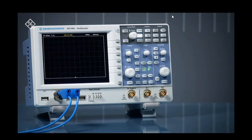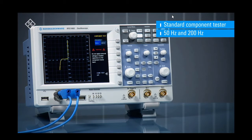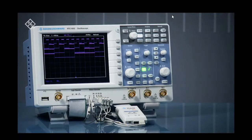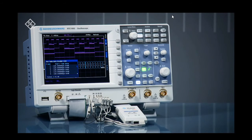R&S RTC1000 series oscilloscopes include a unique component tester as a standard feature. Do you need to check if a component, like a Zener diode, is working? The built-in component tester summarizes thousands of values in one telling diagram. They also feature an 8-channel integrated logic analyzer option. Use the digital channels to see timing relationships, group multiple signals into a bus and see bus values, or view bus activity in a table complete with time tags.